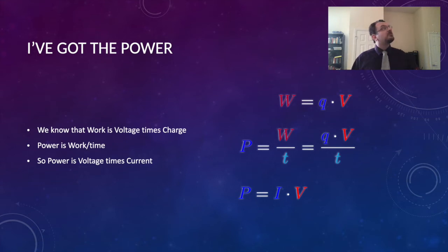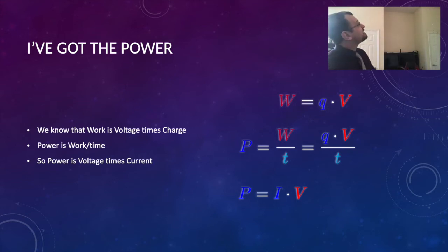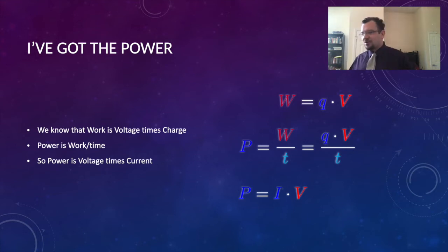So if we return to that light as our example, the voltage is 120 volts because it's hooked up to the wall, and the walls are all about 120 volts. The current, I said that was 1 amp earlier, but how did I know that? Well, I can look at all of the light bulbs in there and see that there are 3 40-watt light bulbs. So with 3 40-watt light bulbs, that's 120 watts. 120 watts divided by 120 volts gives me the current of 1 amp.